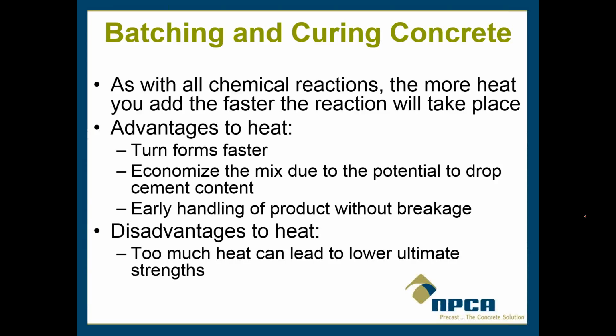So we have to explain to them, and that's what your jobs are out there, is to educate your customers and say, well, actually, the 28-day strength is a specification. It says that it shall not take longer than 28 days to reach this strength. We can reach that strength in 24 hours, or we can reach that strength in 48 hours. So we're not baking cakes, to get back to Kayla's reference. We're making concrete. The nice thing about concrete is we can accelerate the cure.